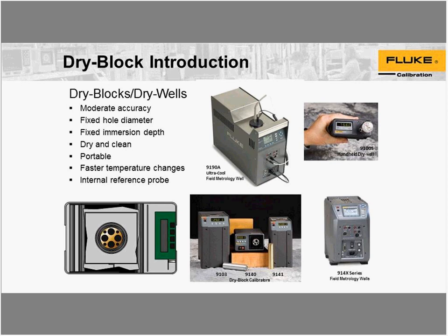All right, so a quick introduction to a dry block. It implies what the title says. It's a heat source designed to be used without any fluids or liquids, hence the term dry. Some of them have fairly moderate accuracy, and they do have a variety of different block designs. Most of the block designs typically have some fixed holes, and then some that are variable. Some have different inserts that are removable. So again, there will be some variation between them.